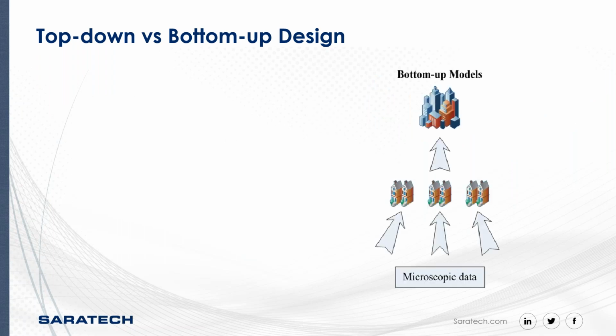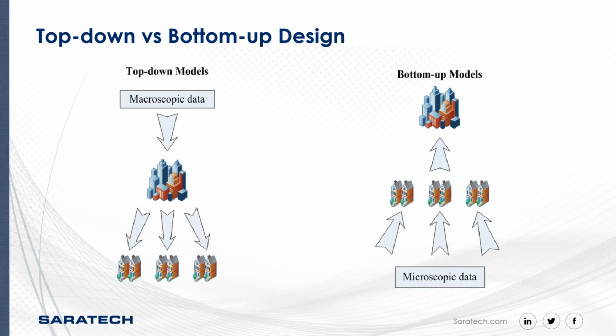All right, so first thing to cover here is two different design theories that we have, a bottom-up theory versus a top-down. So bottom-up really focuses on creating the subcomponents first and assembling and pretty much putting together that high-level design towards the end. So it's a microscopic data approach, rather than top-down, which is macroscopic or driven by requirements by a systems engineer that flows down those features, datums, coordinate systems, critical dimensions down to the subcomponent level.